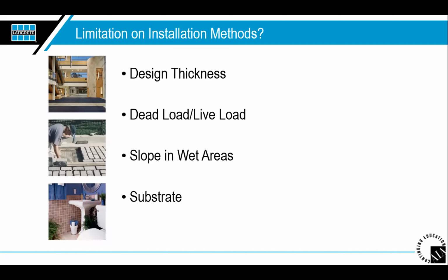Your substrate: not all substrates are suitable for tile, and not all substrates are suitable in particular applications. An example of that would be wood substrates should never have tile directly adhered to them, especially in an exterior environment, right? We have to talk to the installers, and we have to understand as designers and architects what the difference is between your substrate and your underlayment, for example, and how that works. A common misconception that I've dealt with recently, and I've got a great partner in crime who works with me in Indiana, Michigan.